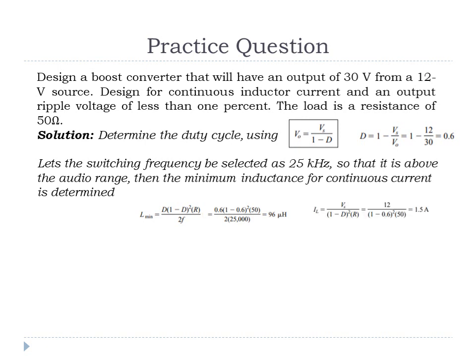Also, the inductor current can be calculated, because we want to find out the IL minimum in the circuit. To keep the margin and to ensure that current is always positive, we select a higher value of inductor, because L minimum is a critical value. So we have to select a value higher than this, and it should be one of the standard values of inductor available in the market.